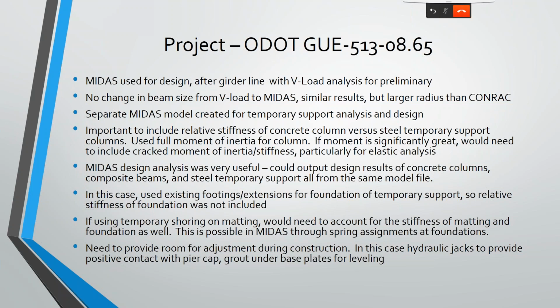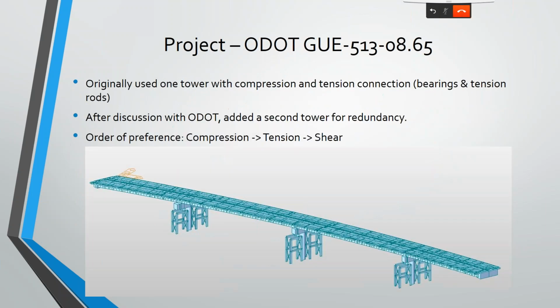And then we've also provided grout under the base plates. We're on top of an existing footing, and you don't know if that footing is level. So you need to provide a provision to get that level and set where it needs to be.